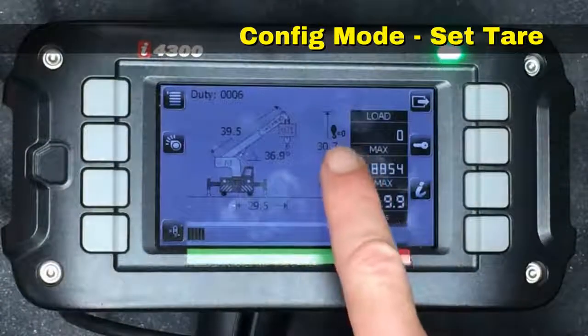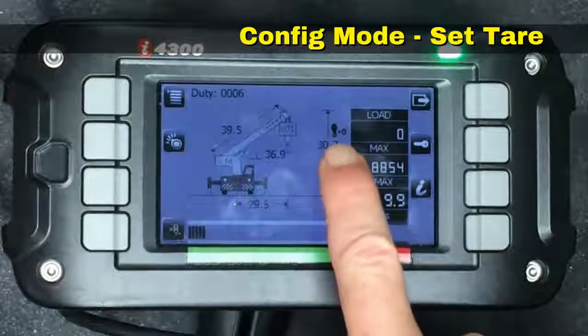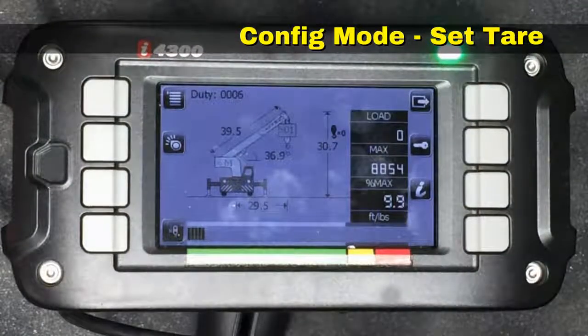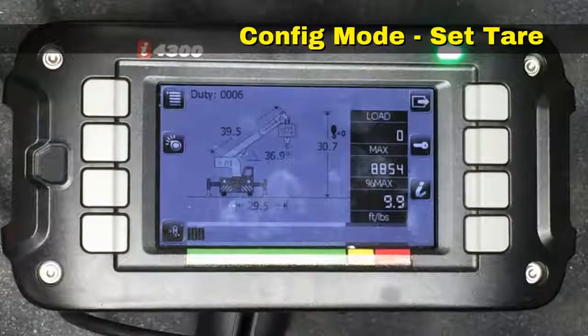And to the left of that, it indicates hook block equal to 0, which tells the operator that he has engaged the tare option. At this point, anything in excess of the load that was present when the button was hit will show up as load on the system. However, when it comes to calculating the maximum capacity, the hook block is still included in that calculation. Anything that was present when you pushed that button is still considered part of the load.